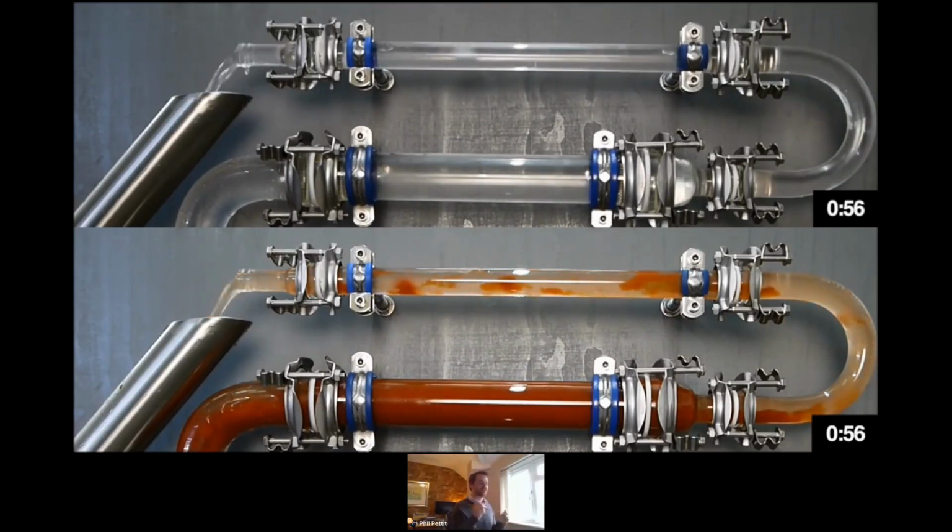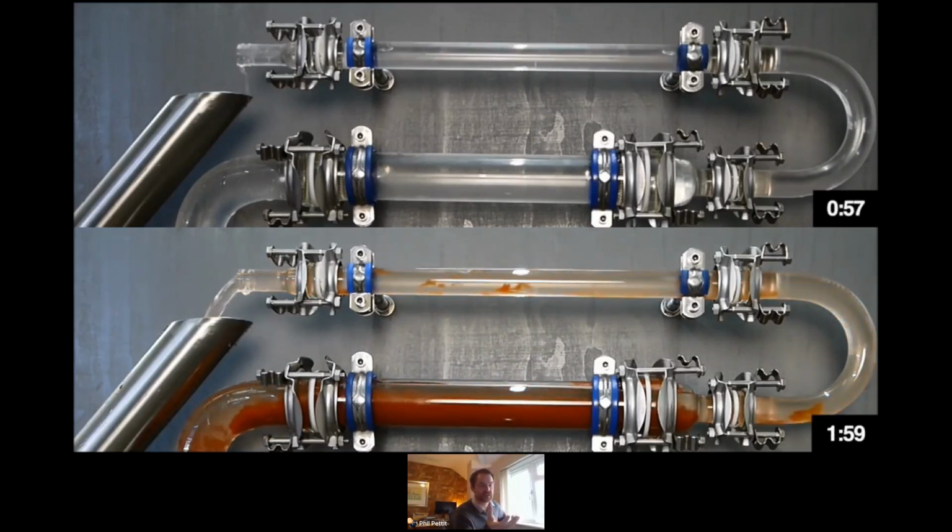So you can see the bottom one where it's being flushed. The top pipe is relatively clean on the small diameter, but the larger diameter pipe is still carrying a lot of fouling due to the lower velocity in that lower pipe. And if you were just going on the colour of that discharge alone,